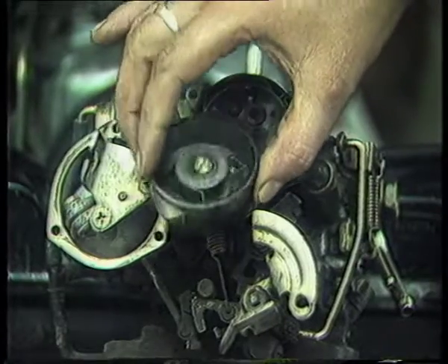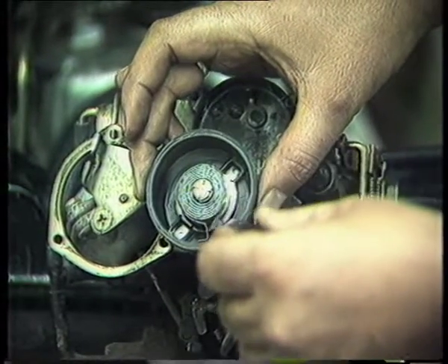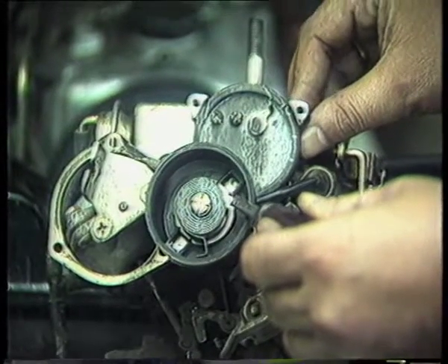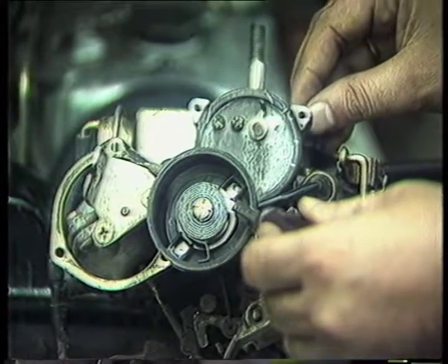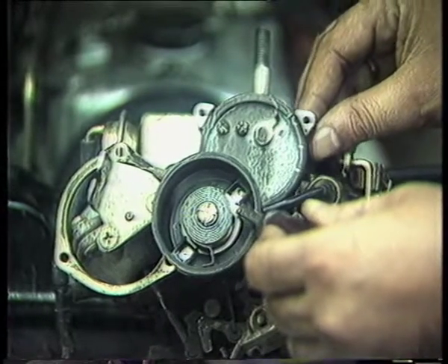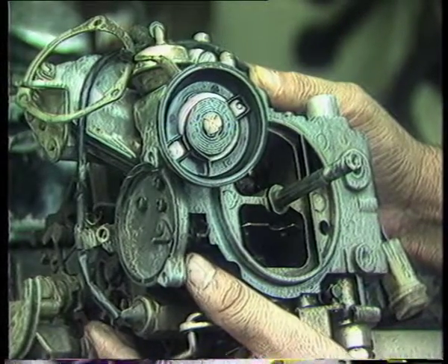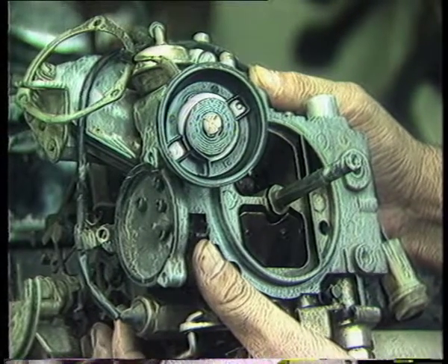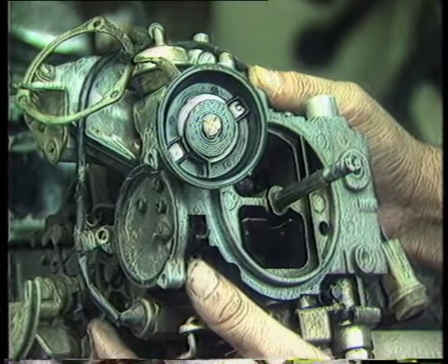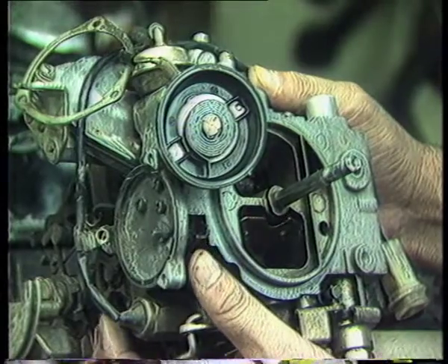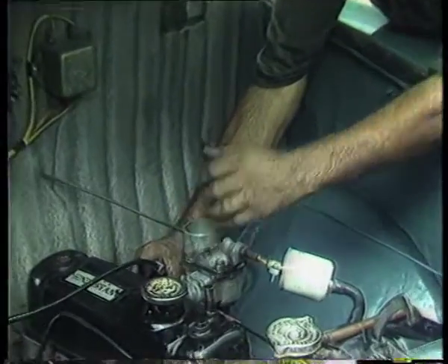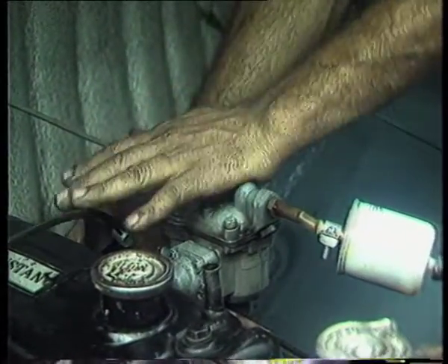The automatic choke includes a thermostatic spring and a vacuum piston, both linked to the choke valve. The thermostatic spring is made up of two different metal strips welded together and formed into a spiral. Owing to differences in expansion rates of the two metals, the thermostatic spring tends to wind up or unwind with changing temperatures. For example, when the engine is cold, the spring has wound up enough to close the choke valve and spring load it in the closed position, and vice versa. Air can also be choked in a very simple way with the palm of the hand to start the engine.